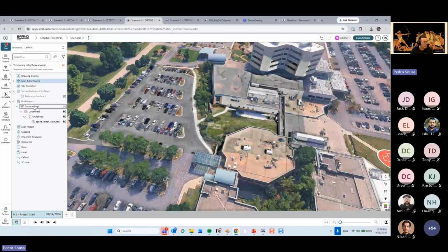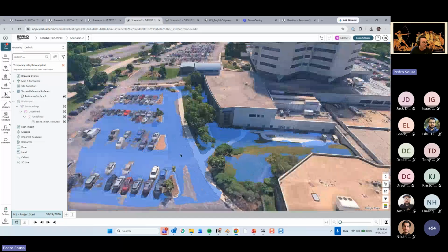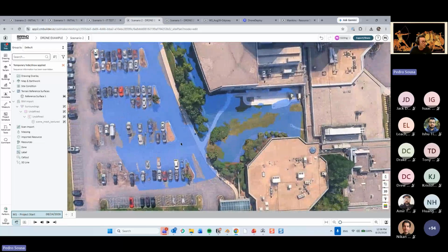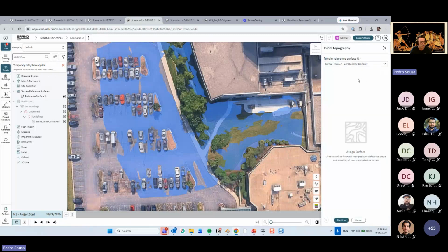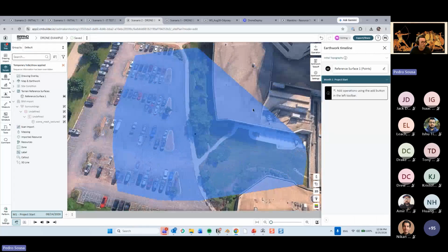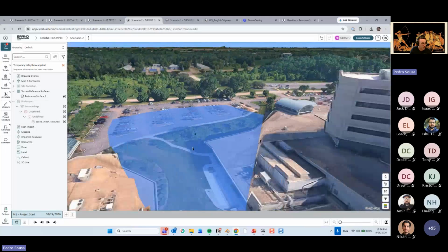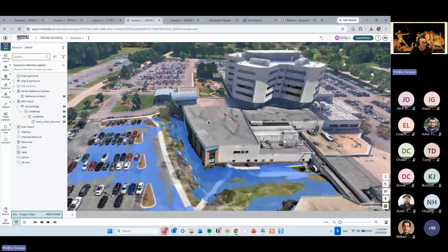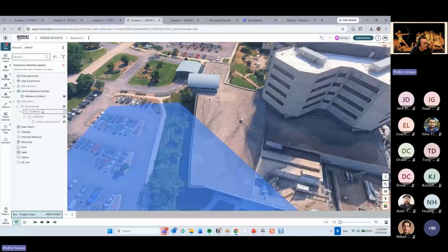So now, if I hide this drone scan, I have a shape of my terrain over here that was created following the drone scan, right? So I will now go ahead and create my initial topography over here with that reference surface, hit confirm, and then that whole area was created following the shape of my terrain. But of course, as you can see, because it created the whole area, it kind of deformed the model, the surrounding buildings on that location and so on and so forth.